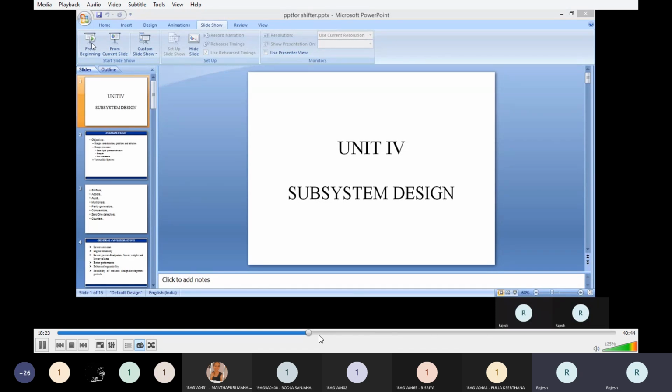So once you have this top-down design approach, you know what are the down designs. Once you have the down designs, what is the down part? Then the part is arithmetic unit and logic unit. And in the arithmetic unit, adders, multipliers, some arithmetic operations, logical operations. So those all are implemented and they are combined to make an ALU. All control blocks are combined to make a control unit, and all memories together form your memory unit. And again together they all become your top unit, the microprocessor.